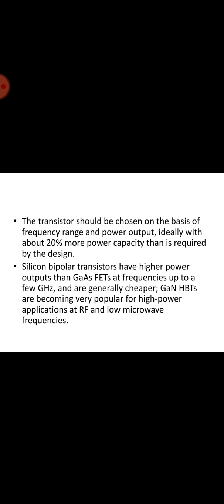Class A amplifiers are ideally linear, and it is sometimes possible to use the small signal scattering parameters for design, but better results are usually obtained if large signal parameters are available. Nonlinear equivalent circuit models can also be developed and used to predict the large signal performance of FETs and BJTs. The dominant nonlinear parameters for a microwave FET are, as I said earlier, CGS and related parameters. Equivalent circuit models can be very useful when combined with computer aided design software.